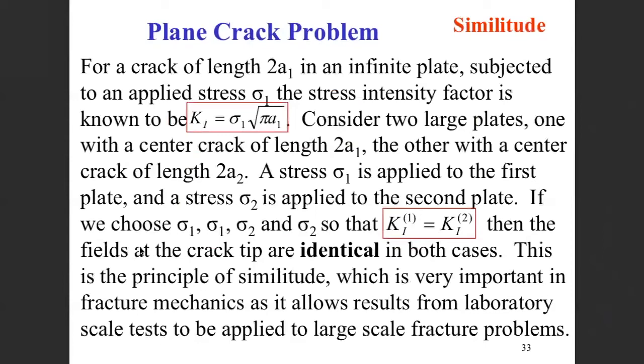So if you have two plates, one with a crack of some length and one with a different crack, if you apply a load such that the stress intensity factors for those two cracks are the same, then the stress field and strain field at the tip of that crack are identical in both cases, right? So it's a way of doing the analysis that normalizes out all of the geometry, right?